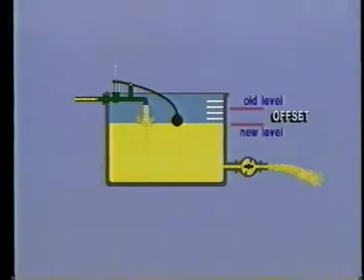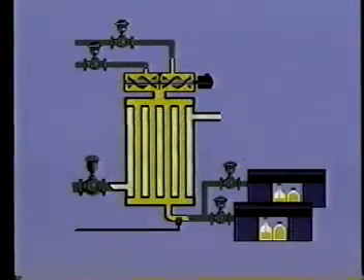In other words, the water level has been offset. It is clear then that in the event of a large load change, proportional action simply isn't enough. Similarly, in the chemical plant, proportional action alone was not adequate to return the temperature to the set point during load changes. An additional control action was needed, one that would open the valve beyond that of proportional action whenever the second bottler was turned on.